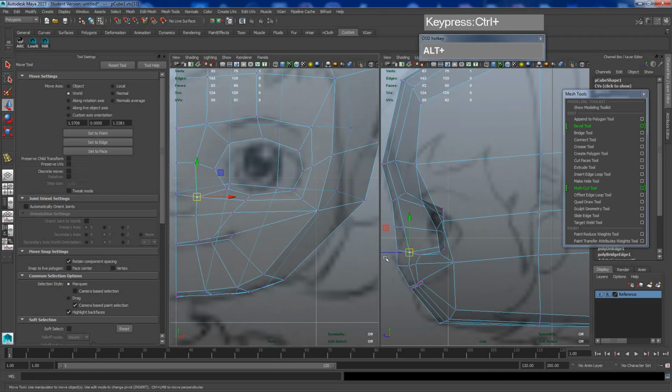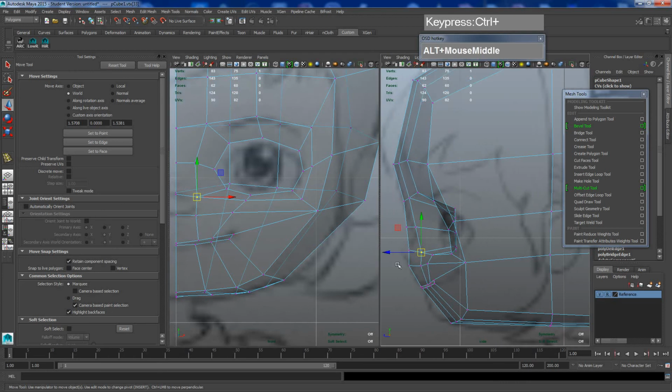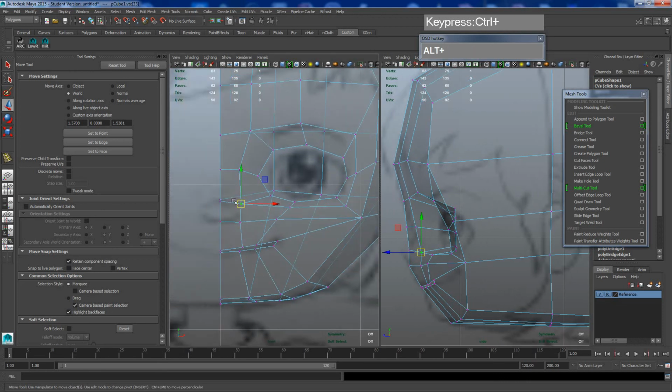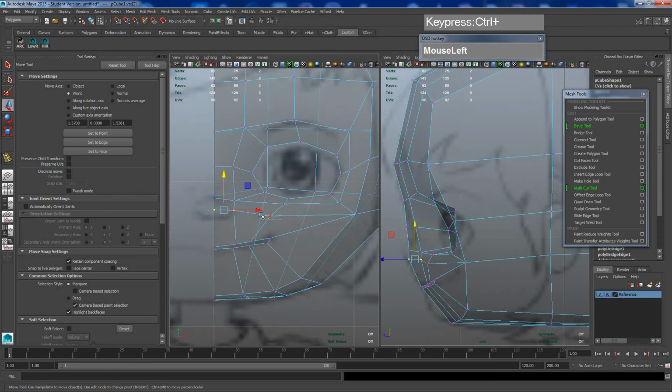Okay, at this point in time, we have sufficient faces, or rather, we still need one more face, 2 adjacent faces to create the nose. So I'm just going to push this. Okay, now this is a continuous edge loop that runs across to the cheek and all the way down. Okay, you can confirm by double-clicking on this. Okay, actually it runs to the end and it stops here because there's a multi-point vertex star here.